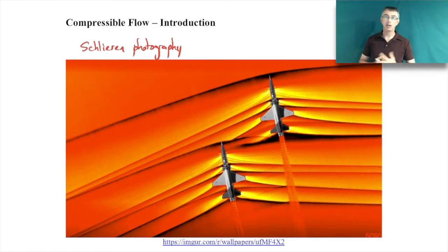and such. Shock waves, as we'll learn about in another lecture, are where you get very abrupt changes in the air density, the air temperature, the pressure, and the velocity. And they only occur in supersonic flows. So that's a topic we'll talk about later. So that's one big difference between compressible flow and incompressible flow, is that with a compressible flow you can get these kinds of shock waves that occur. And we'll talk about later why they occur and how we would analyze them.